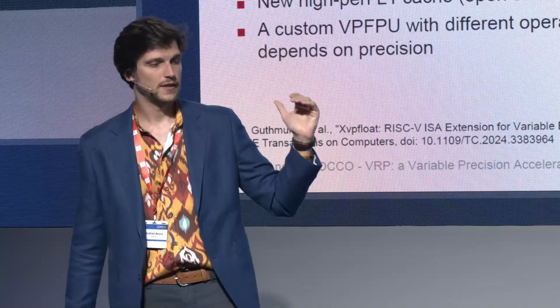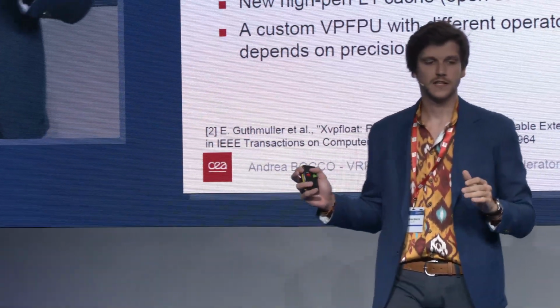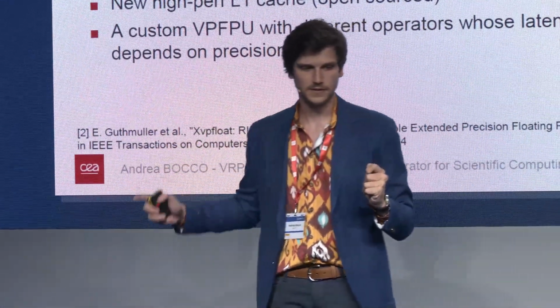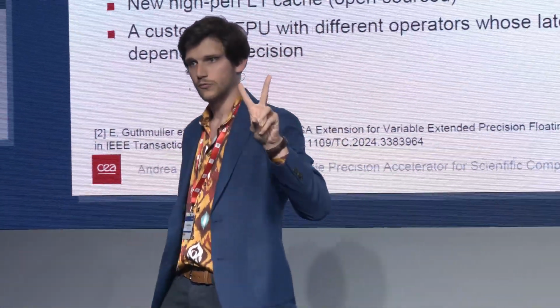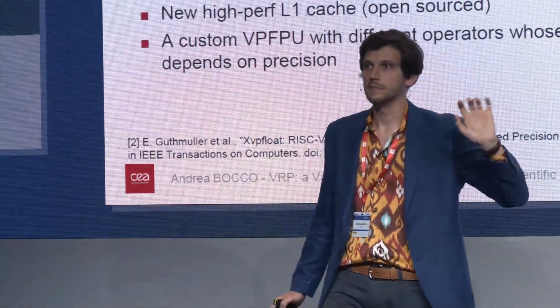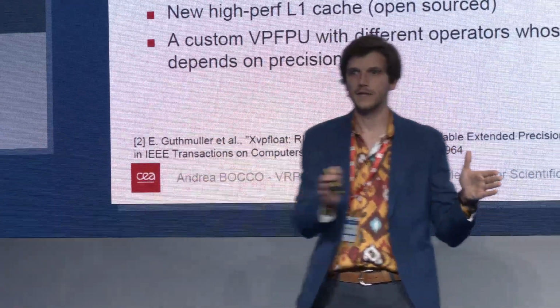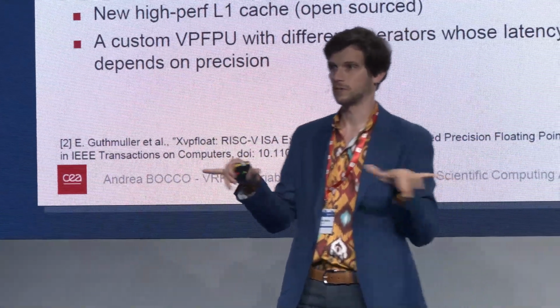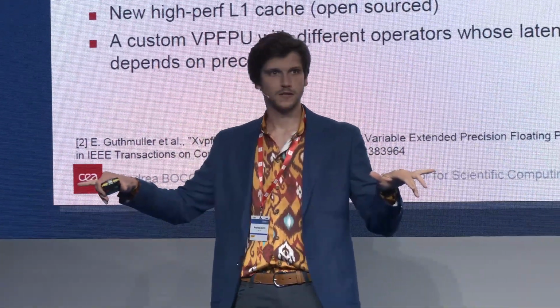The main thing is that we want to support higher precision floating point data in memory. We have 32 logical, 64 physical registers that support up to 512-bit mantissas. We have two categories of formats. The first one in memory, where we can tune the precision, the size of the data, at bit level, and we support misaligned data in memory as well.